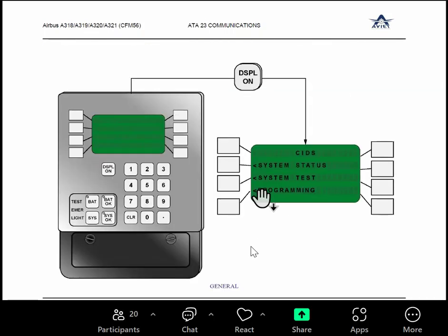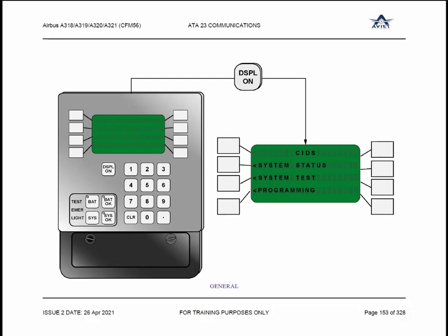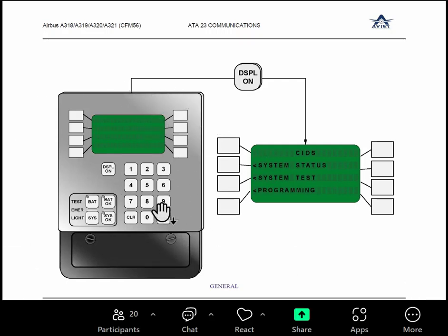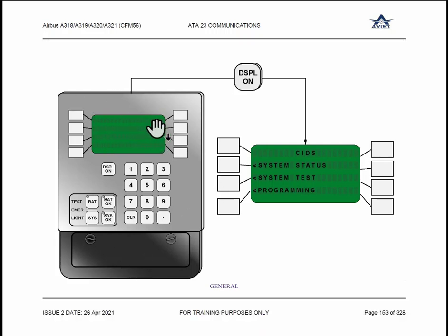System. That's a PTP, Programming and Test Panel. It is an interface unit like the MCDU, which is used for many maintenance functions and configuration functions. It is behind the panel, so normally you will not see it. Once you open the panel, you will see it has an MCDU-like structure. Keyboard is there, line keys are there, display unit is there.